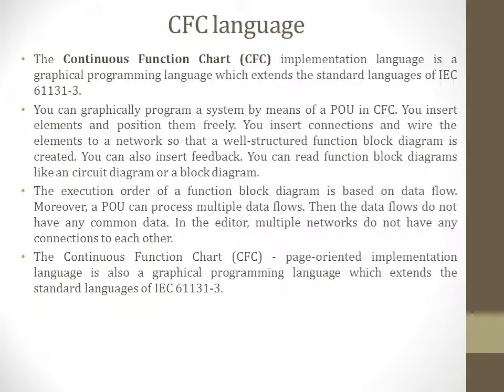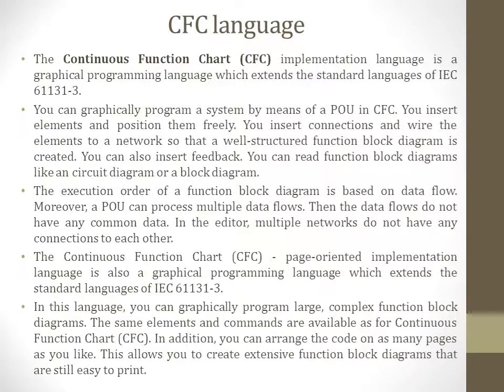The CFC page-oriented implementation language is also a graphical programming language which extends the standard languages of the standard. In this language, you can graphically program large, complex function block diagrams. The same elements and commands are available as for continuous function chart.